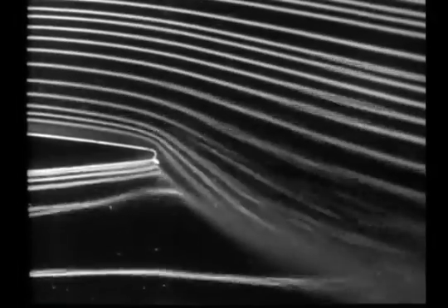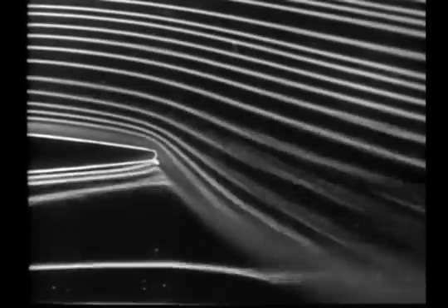When the jet is rotated and issues into the free stream at an angle, it is gradually turned, the rate of curvature depending upon the relative velocities and the fluid momentum. Each element of the jet sheet is subjected to a centrifugal force, which is in turn just balanced by pressure forces. The curved sheet thus supports a pressure difference, much as if it was a solid flap.